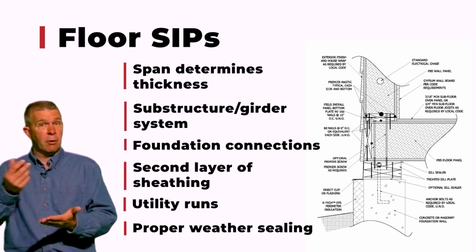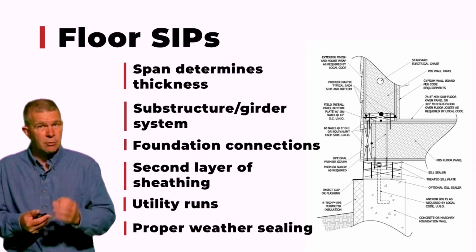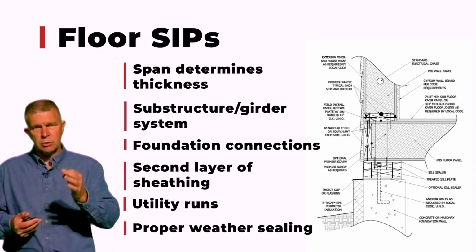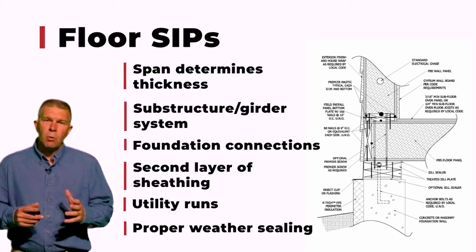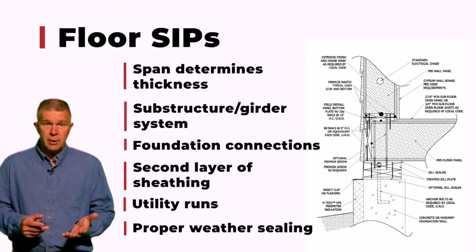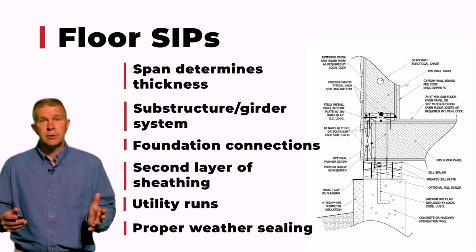And then if we put another layer of sheathing on top of that panel, we're now talking about trapping moisture. So it's really important before you consider using these floor SIPs. So the designer, when working with floor SIPs, they need to determine all of those various things.